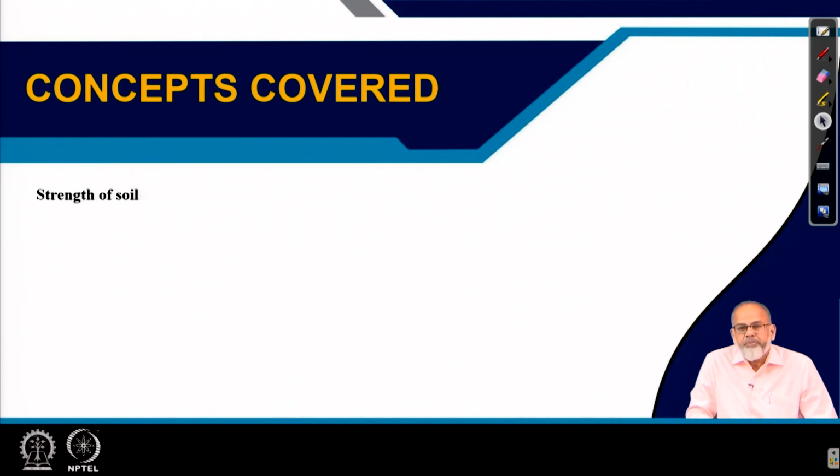So that's why this parameter is important, and there is a standard defined by the American Society of Agricultural and Biological Engineers on how to measure strength of soil. In this class I will try to follow that standard, and explain how to utilize those procedures in measuring the cone index. Basically we will take a static cone penetrometer, and that has to be pushed into the soil at a steady rate. How I am going to utilize the cone penetrometer in the soil bin, I am going to demonstrate.